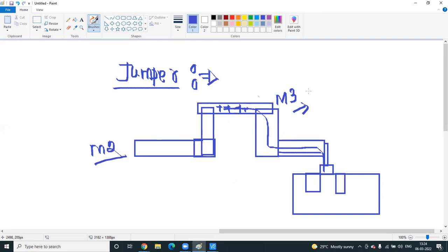So if you calculate the metal area by gate area antenna ratio, if you calculate only up to this, it will definitely come. And if you place a nearby jumper, definitely the metal area by gate area will be less. Understood, or any doubt till now?